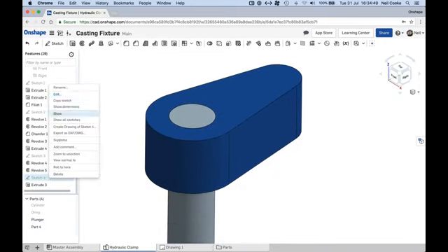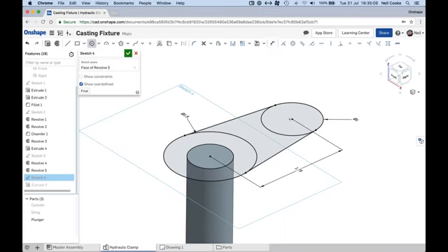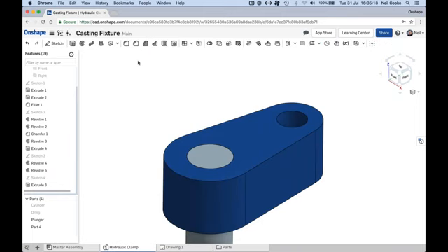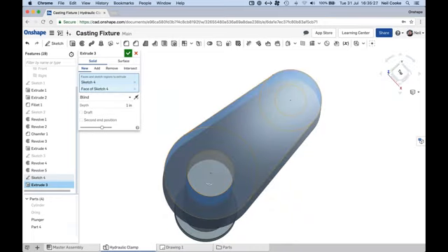Okay, let's just go back in and edit that sketch real quick, and let's just add a couple of dimensions. So adding dimensions, as you expect, there's just one command, and it's whichever geometry you select and wherever you place it, so it's going to make a lot of sense. So just give that a size and make that 1 inch, and we'll just add another circle in here and make that 0.5. Okay, now the fact that I've added another contour in here, when I click OK on that, it's going to add the hole in. If that is not correct, you can edit the actual extrude feature by double clicking, and just by clicking the area, you can include that in the sketch if you wish.